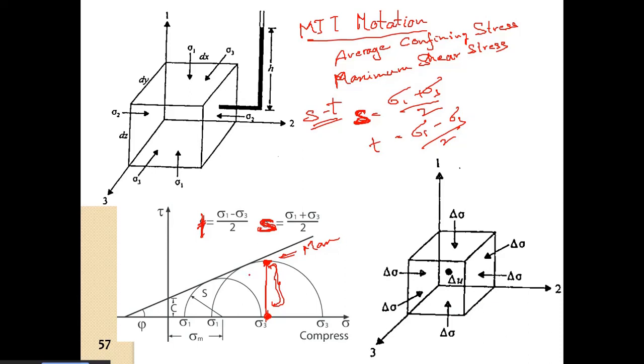All right, so if we move on to another plane, we can see that the shear stress will reduce. So this is the maximum value of the shear stress, tau max. It is very easy to see from here. If we rotate the plane, the shear stress will reduce. It will not go beyond this for this particular stress configuration, of course.